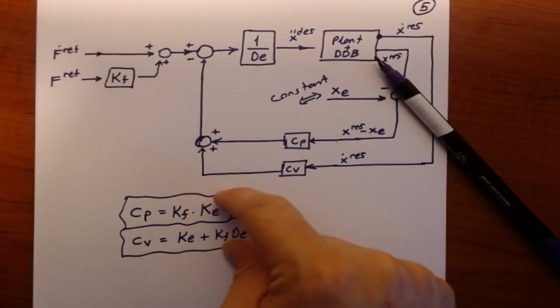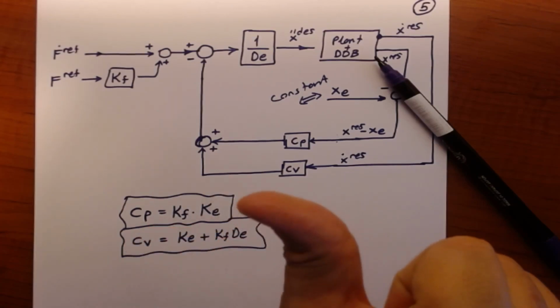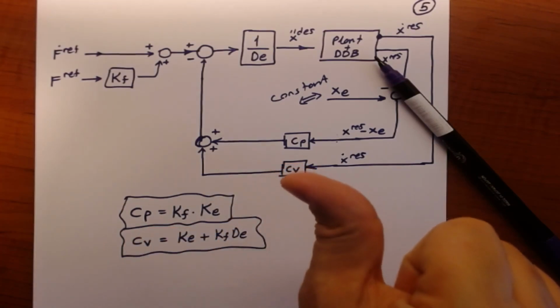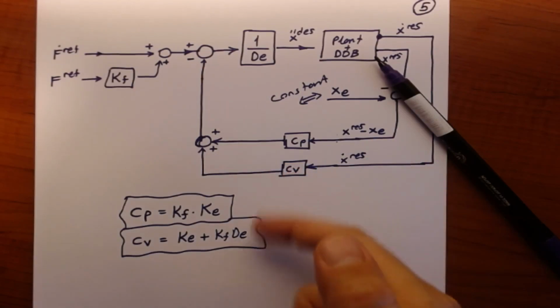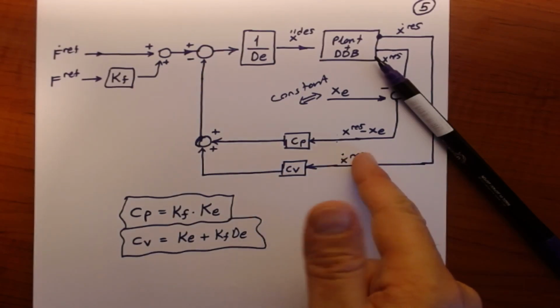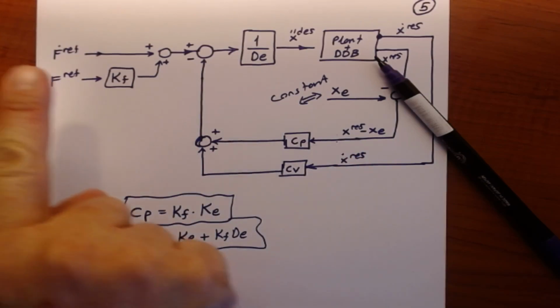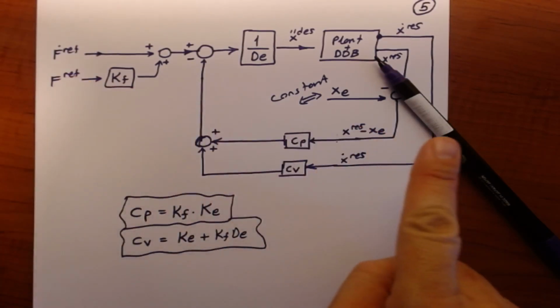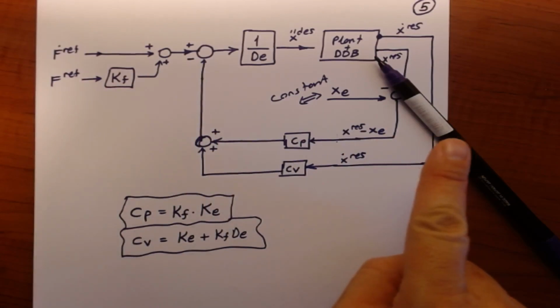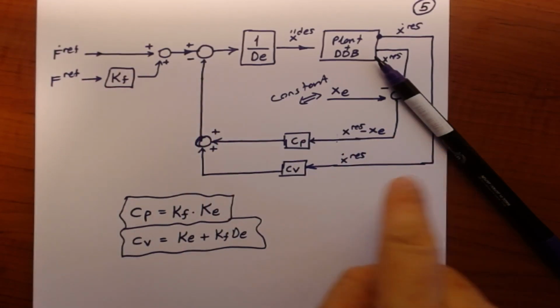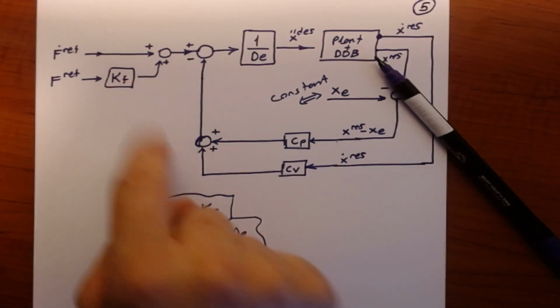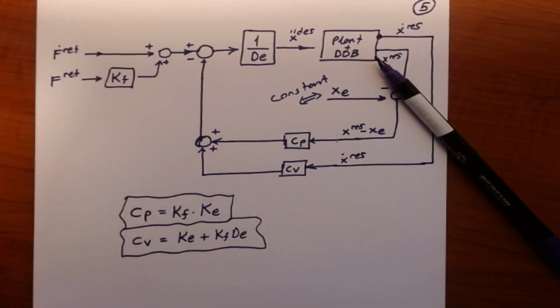Both of these models are valid, and taking an additional velocity feedback on the pure spring model, or using the spring damper model directly, you have natural behavior of the robot. Your robot approaches the environment with velocity feedback, and when it contacts the environment, it moves to force control mode directly with this algorithm.